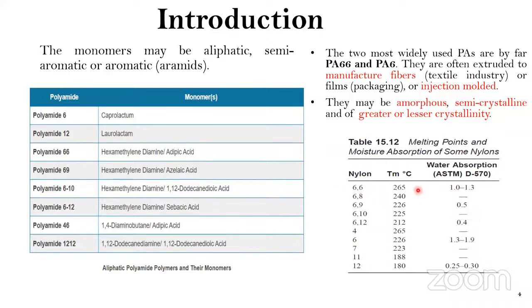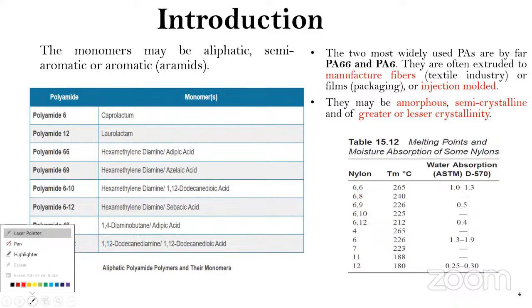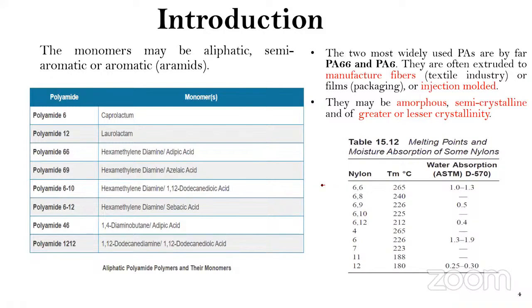And the melting point of nylon 6,6 is 265. That is the reason whenever you use nylon 6,6 for your manufacturing, you have to do the pre-drying process. Similarly for nylon 6, because the melting point of nylon 6 is also around 220 degrees Celsius. So if you see how the structure of the acid group is changing, or how we are increasing the carbon content, can you see here first 6 carbon, then here your carbon amount is 8, and this all represent the